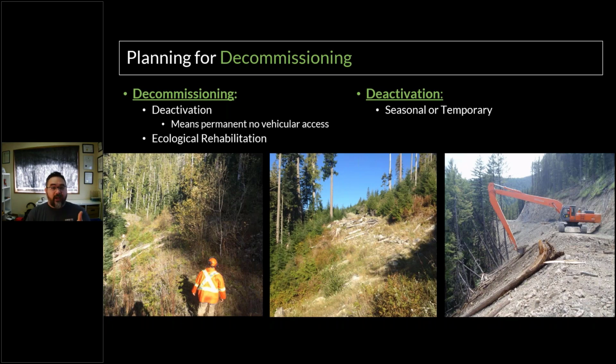Or maybe on our crossings, we'll have modified fords. That is a swale with pipes that carry low flows, where we can just remove those pipes and the surfacing and just leave a rock swale in as we deactivate that road. So knowing that lifespan, you can design those things up front. And again, that planning process gives you the ability and the time to do it thoughtfully right from the start.